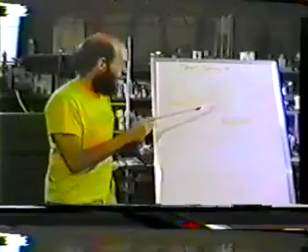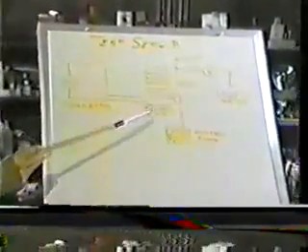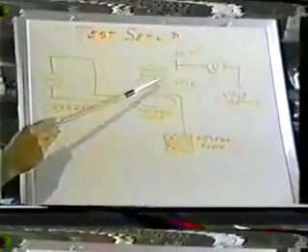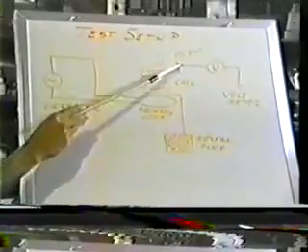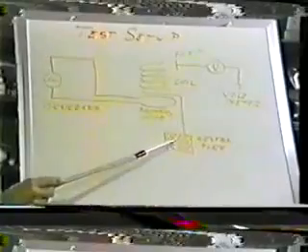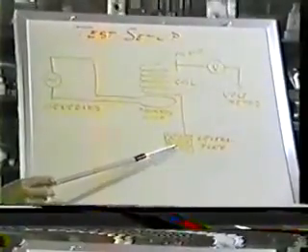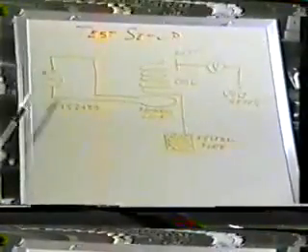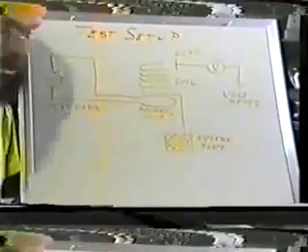Okay, now we have our longitudinal wave test setup. Again, we have the same generator. This time our transformer couples the generator energy to the first turn of the coil, which is wound of fairly fine wire. And then we have a capacitive probe pickup to measure the voltage rise at the end of this coil. And at the neutral end of the coil, we have a large capacitance plate to produce our impedance dissimilarity, so we end up with a quarter wavelength rather than a half wavelength resonance on this coil. Now we'll look at our test setup again here.